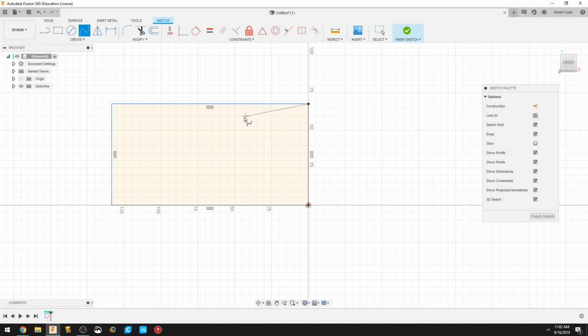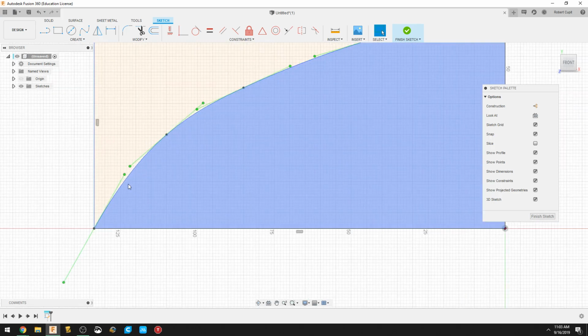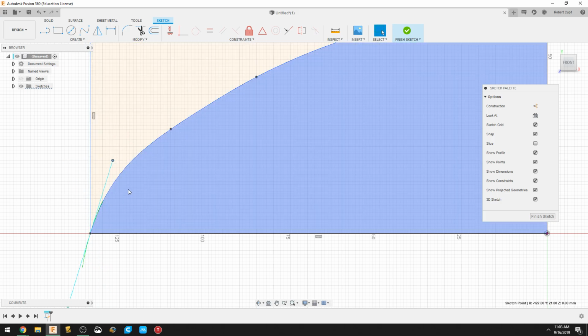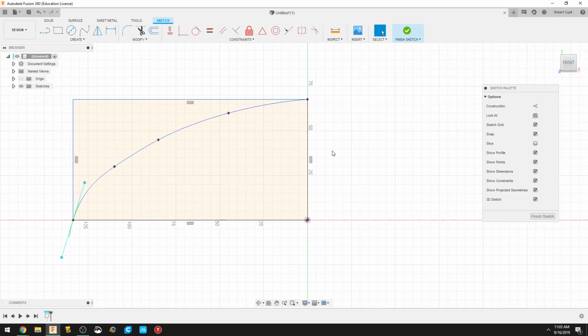I'll go here, and if you look at the drawing, there are 3 dots, and then it clicks here. You can bend this and twist this. I'm not holding it. I clicked once and let go. And then at the end, you can either press Enter or right-click and press OK. Now, what a spline can do is with these green vertices, you can manipulate that line and make it whatever you want later on. We're not going to do that. That's the whole point of this spline.